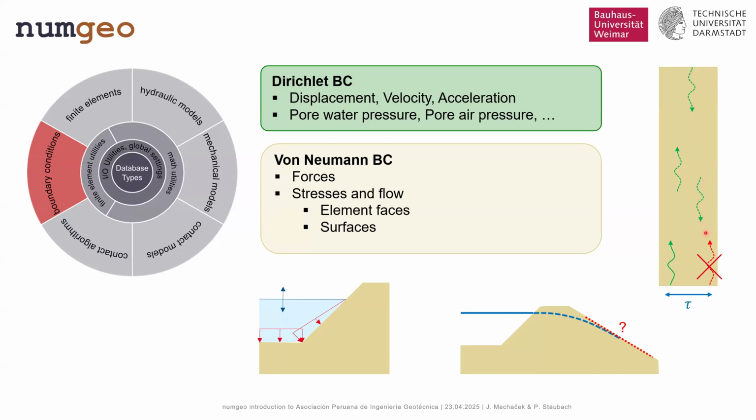And if you have not a proper boundary condition, this signal will be reflected at the base again and travel back to the top through the soil column. And obviously, usually, if this is not a bedrock at the base, we want to prevent that because the waves could, in reality, travel through the base of our model. And this can be prevented by using such compliant-base boundary conditions.